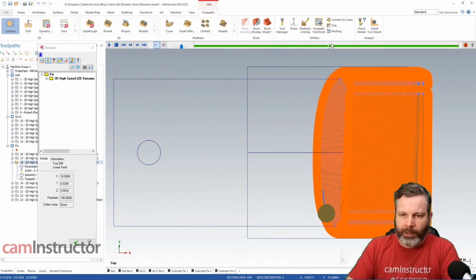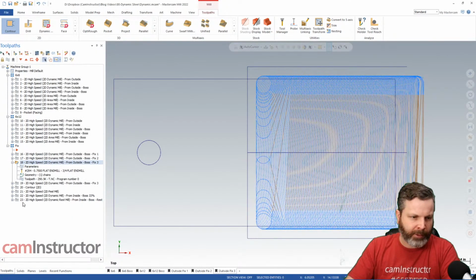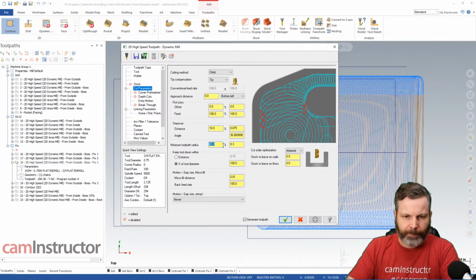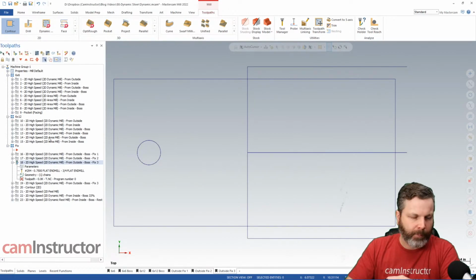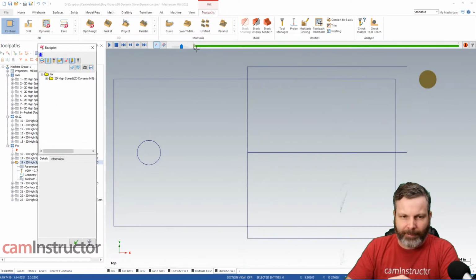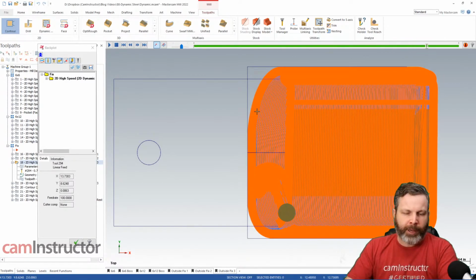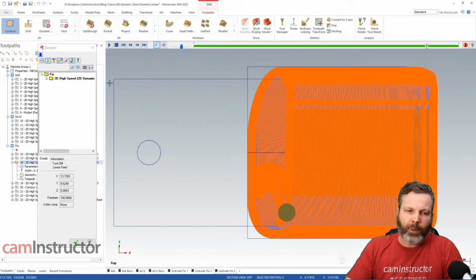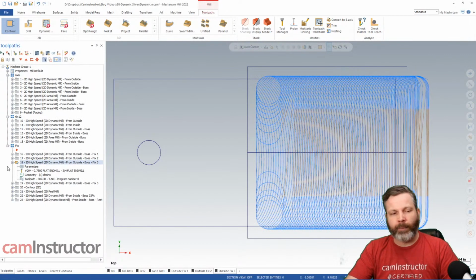And then also we need to keep in mind, if we were to do a path like this, that's not exaggerated enough. That's probably still not exaggerated enough. Okay, so let's pretend our toolpath ended right there. We would need a way to give the next toolpath all of this missed material for the operation to see.